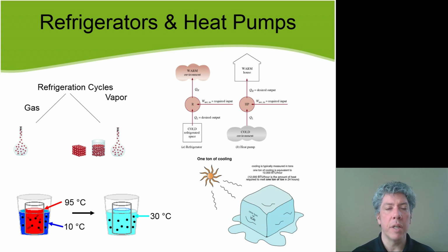And so let's say you have 1 ton of water, and it's at 0 degrees Celsius, okay? If you have a refrigeration system that has a 1 ton capacity, what that means is that that refrigeration system could take that ton of water that's already at 0 degrees but not solid and transform it into solid water, all ice, at 0 degrees Celsius. That's what it means. So it has more to do with the latent heat of fusion of water than anything else. Of course, the quantity is where the ton comes from.